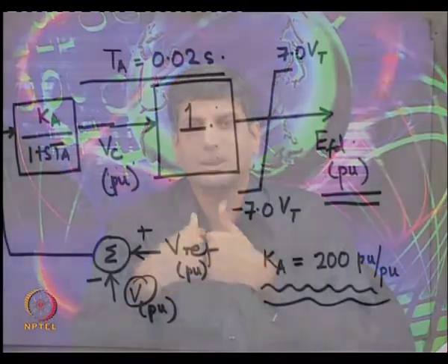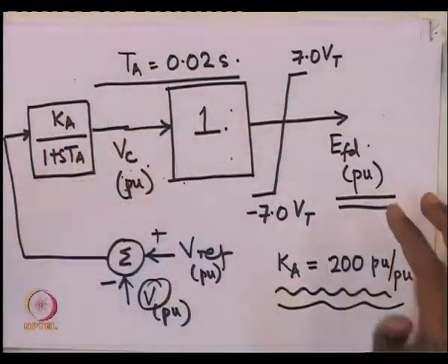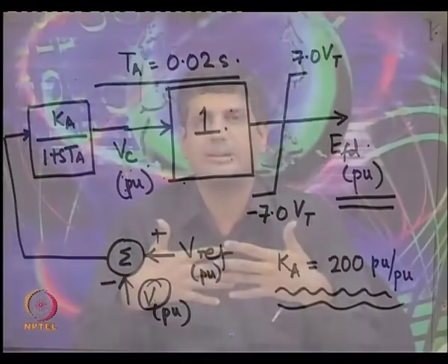We could have included many more possibilities. In fact, in this course we will not do that. We will include a simple excitation system model, using a static exciter, and this we will use to study the voltage regulation of a synchronous machine. What I will do is now incorporate the equations which are embodied in this transfer function or these limiter and summer blocks, write them as state space equations, interface them with the synchronous generator equations, connect a synchronous machine to another voltage source, and try to regulate the terminal voltage of the synchronous machine.